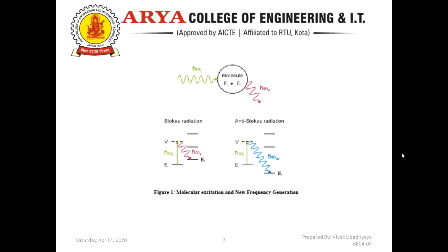The Stokes wave has a frequency downshift of 13.2 THz. This means that if a signal shifted by 13.2 THz enters a region having excited molecular levels by a suitable pump wavelength, amplification of the signal occurs. This is the basic principle of the Raman amplifier.